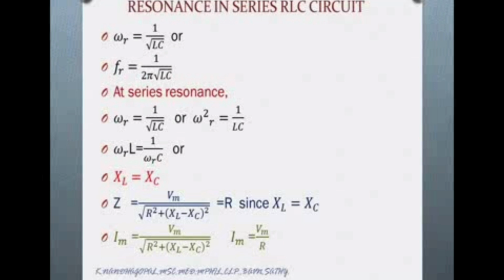So all the input circuits have the capacitors and inductors inside that circuit. So when the two reactances are equal, the impedance becomes minimum and the flow of current is maximum. So it is used in the tuning circuits for the television and the radio, or the other communication systems also, right? So this is the use or the application of the RLC resonance circuit.